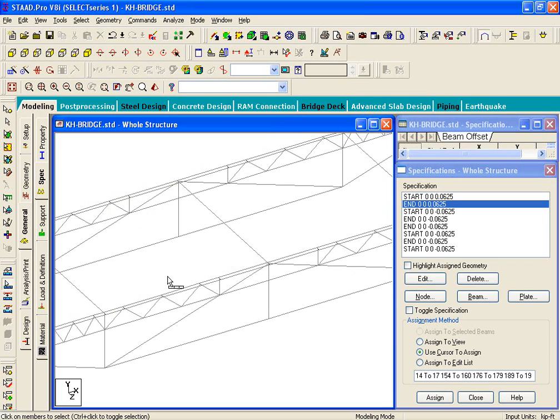The advantage of using physical beams is when you define your loadings. In the AISC steel bridge competition manual, they give you the loadings from the start node of the bridge. So, say X equals 6 feet from the start. You don't want to be playing around with analytical pieces when you apply these loadings. It would be much easier if you had the physical beams formed, and that's why we've done that.